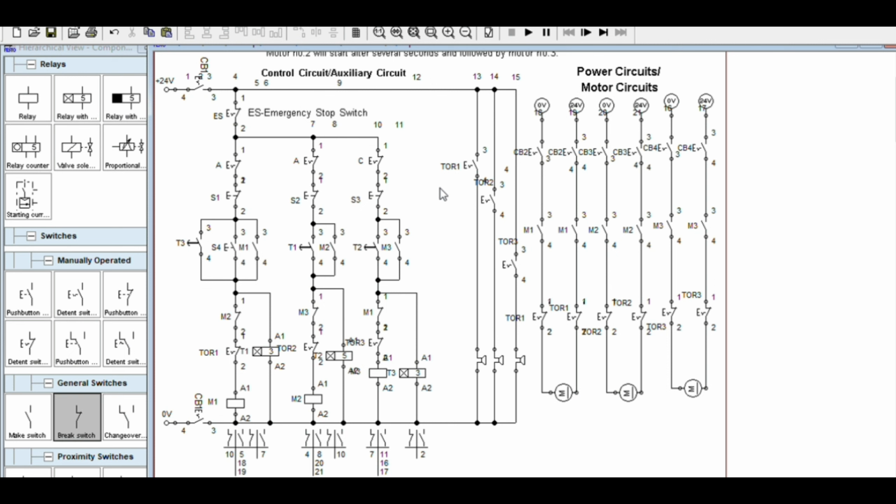So the safer way for this is to add an auxiliary contactor. That means you turn this off first, or finish the operation here first and then transfer there. So there is no way that this one will act first before that one opens. Although we don't have the timer here, we need another timer. You can also use the normally closed contact of this timer. Placing the normally closed timer here is not possible, because this won't operate.